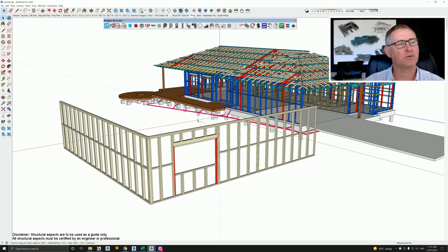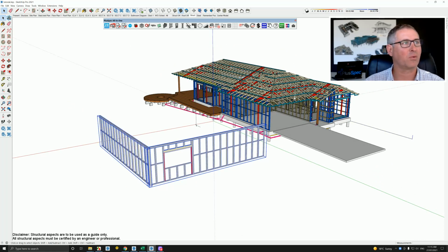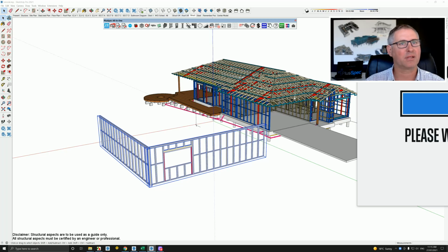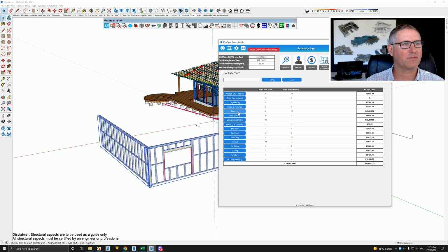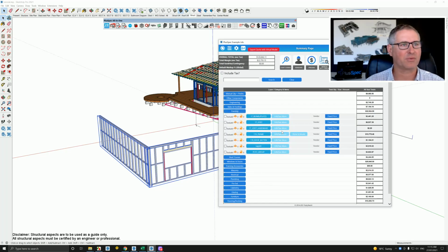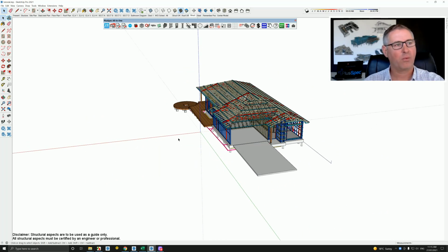So we look at our structural. It enables you to associate price. So if we said let's do a bill of quantities on these particular items here, I'll bring that over. Right, so everything inside of those walls is there. So if I looked at my framing, it's going to tell me how much framing is required. If I looked at my cladding or my bricks, it tells me how many bricks are required. And you'll notice that we can associate price with these items, and therefore we can get an understanding of the feasibility of the project before we actually lodge it into council.